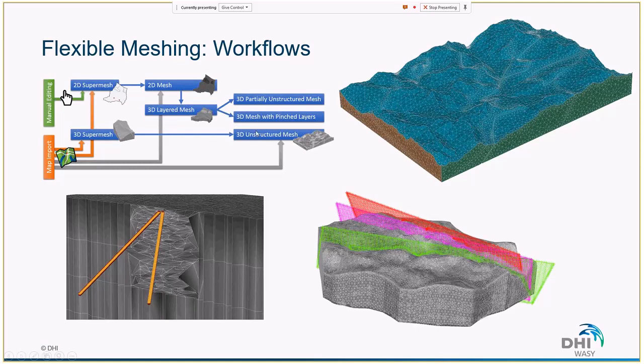And there are multiple advantages here because how you prepare the data can help you accelerate the process. If you already know that you have multiple geological units, you can set your input data in a smart manner so that FEFLOW can store the elements inside each unit in multiple groups, which then makes it really easy to assign material properties. You just need one single click, activate the group, and then set your conductivity to 10 to the minus 4 meters per second, for example.